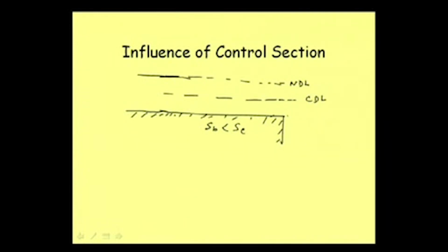And then when there is a free fall, overfall, so this drop, canal drop or whatever it is there, the flow will have to go like this, and then actually this water profile will start from this point and it will be coming here and it is meeting. So, this profile is basically M2 profile. Now this profile is moving like that and it is meeting the CDL line normally at this point.